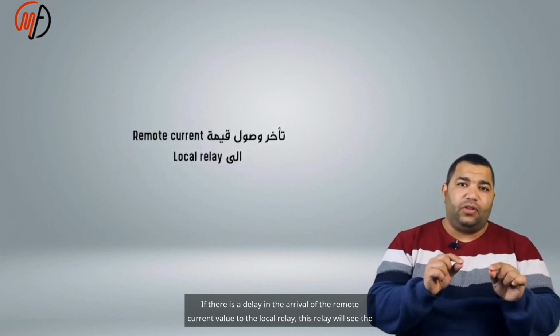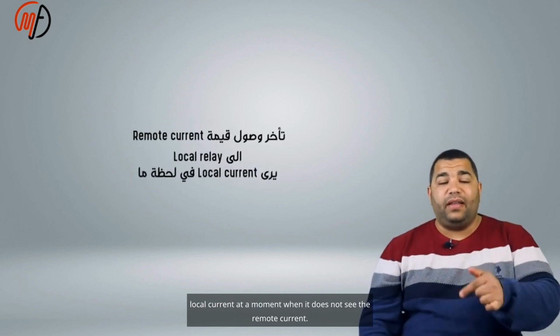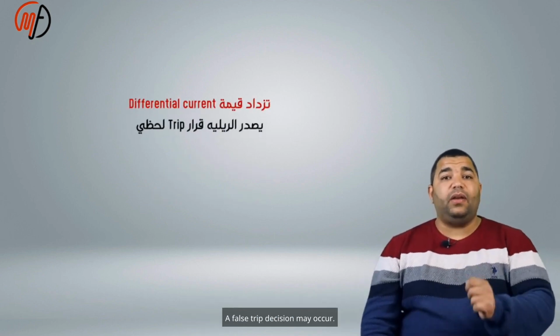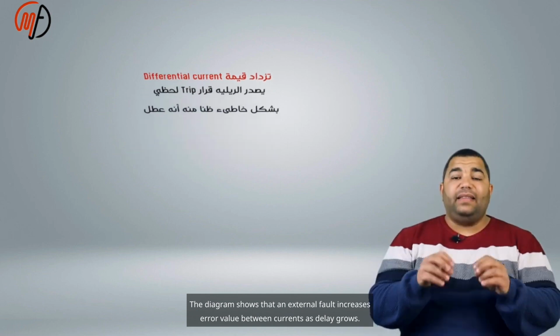If there is a delay in the arrival of the remote current value to the local relay, this relay will see the local current at a moment when it does not see the remote current. At that moment, the value of the differential current will increase. A false trip decision may occur. The diagram shows that an external fault increases the error value between currents as delay grows.